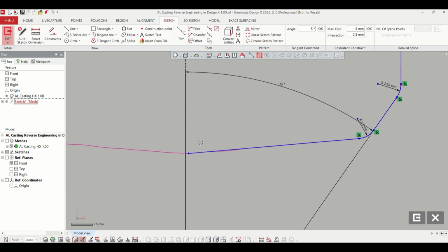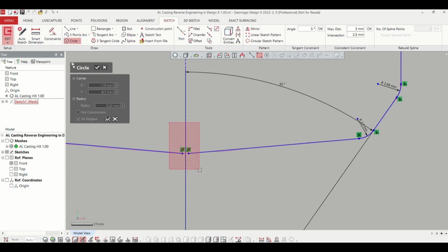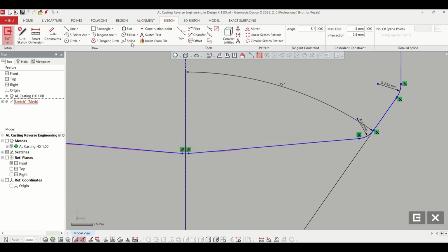So to think through that a bit, let's first off do a mirror image of that bottom line segment. We'll call this the line of symmetry, of course. Specify this entity. It automatically creates the mirror image of that line. Now we want to do a best fit on just a small portion of that arc, 20.22. Looks good. We'll put in a fillet, 20.22 between these two line segments, and we'll trim that arc and delete that line.